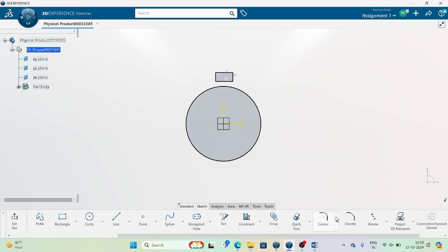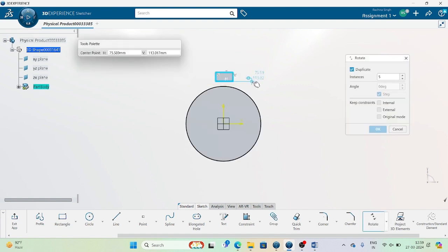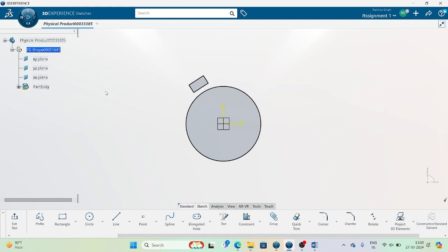Now here also the same thing, duplicate. If I want to choose this one, I want to turn off the duplicate, select the center point, select the angle. Sorry, my selection process is wrong. Select in the box entity like this, select the center of the point and check duplicate and give the angle. So you can see. This is how we can create. Now if I want the same object to be placed here also, one object, in that case we can use the mirror command. Clear?